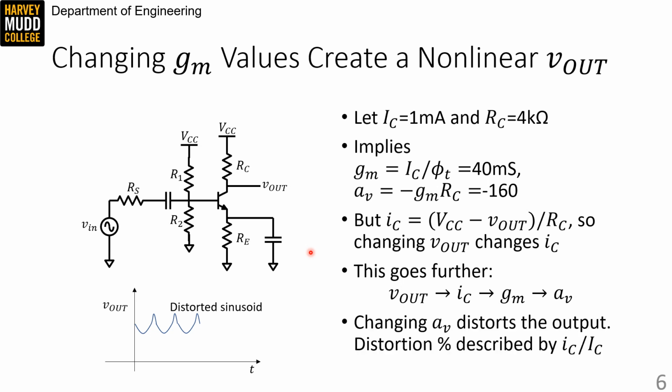So if Av changes as our output voltage moves around, that'll result in an output wave that looks different than the input wave. Some parts will be amplified more than we'd expect, and some parts will be amplified less. So predicting the exact shape of the wave is involved, but you can get a quick guess at your percent error at any given output voltage by taking the ratio of your gain to the gain you are aiming for, which, if you follow the math through, is the same thing as taking your instantaneous total signal current divided by the large signal current that you presume is always running.